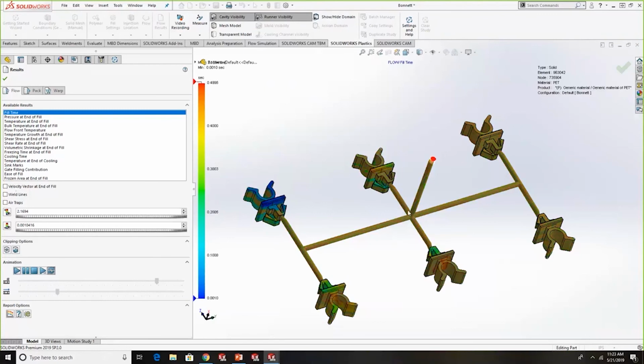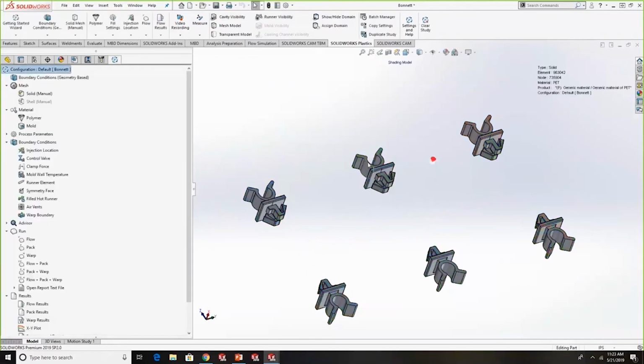So the great thing about this, obviously some of you tool makers probably already understand. You're like, oh yeah, it's pretty easy to see. The 2 cavities closest to the runner have a very large diameter, and you're probably already well aware of that. But sometimes it's still iteration in terms of figuring out what the appropriate runner is for balanced running. So one of the things you can do with SOLIDWORKS Plastics is tell the program to solve for what the diameters are going to be for the runners.